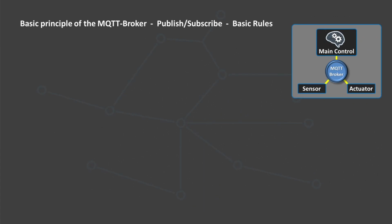The MQTT broker controls the publish-subscribe mechanisms for the signal distribution. A client, for example a sensor, offers its information to the system by a publish to the MQTT broker.